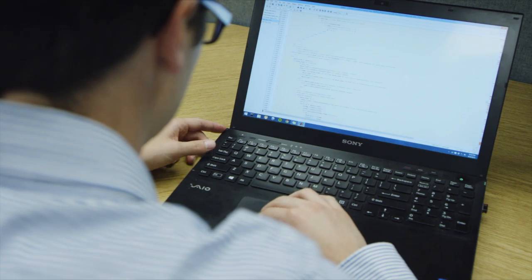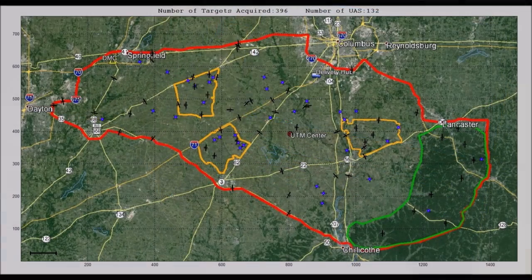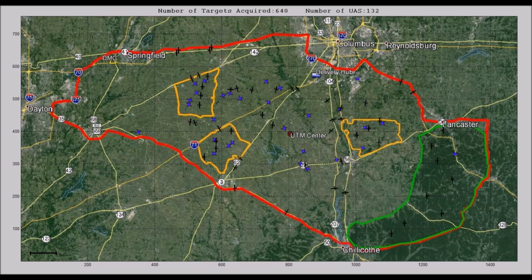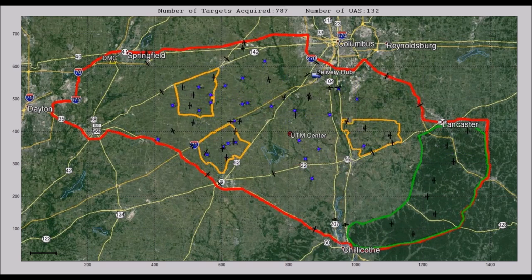So when trying to, for example, locate the position of an aircraft, you have very different sources of where that information could be coming from. It could be coming from several radar sources, from a transponder, from GPS, for example. What you have to do is take all these different sources of information and make sure you're using the correct one, the most reliable source that you can. So what I'm doing basically is developing a data fusion algorithm to take all of those different sources of information and trying to select the most accurate one for our case.